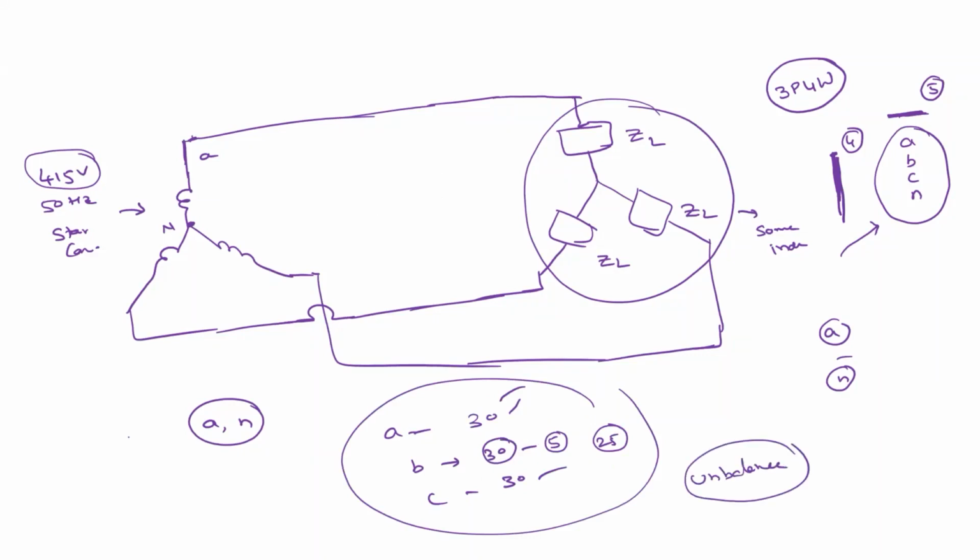Agree? So this balanced load will become an unbalanced load. Since they are only parallel, the voltages will be the same. Yes, they're only parallel to the voltages, but the currents are unbalanced. The voltages are balanced, the currents are the problem.